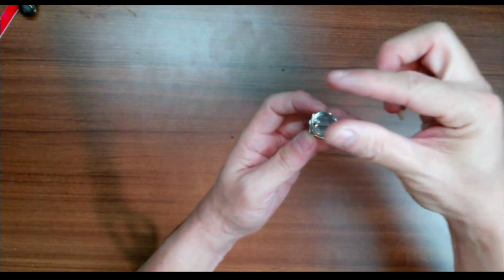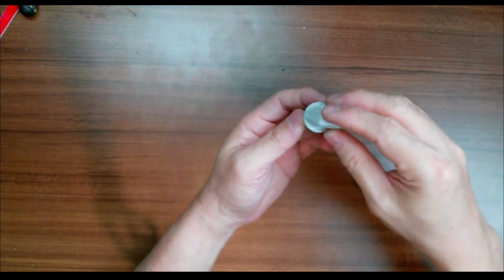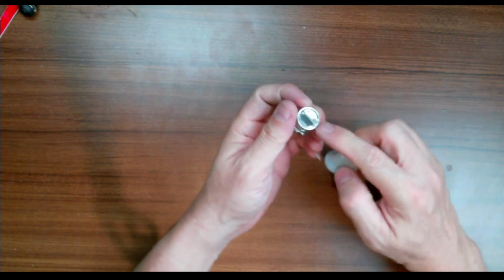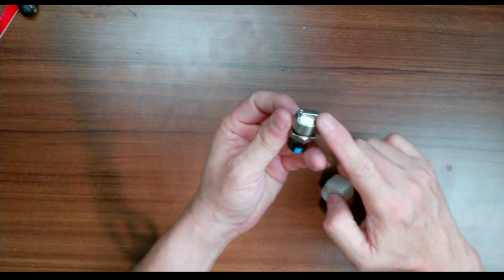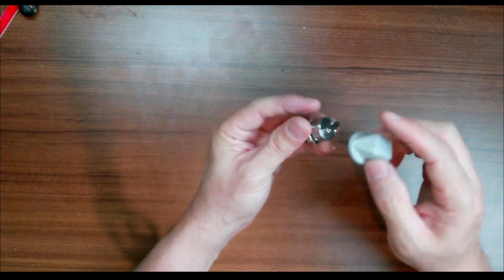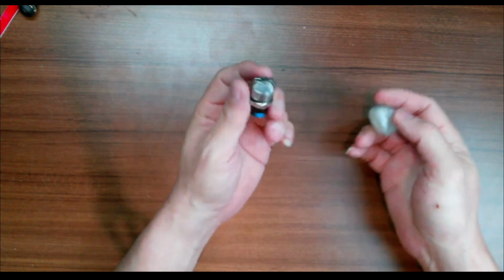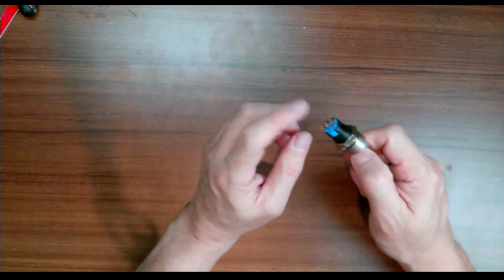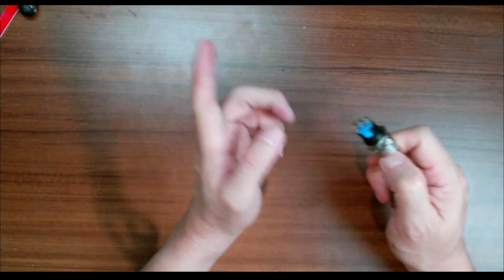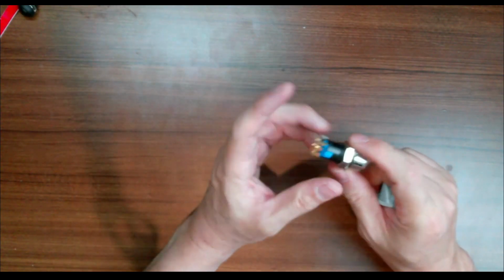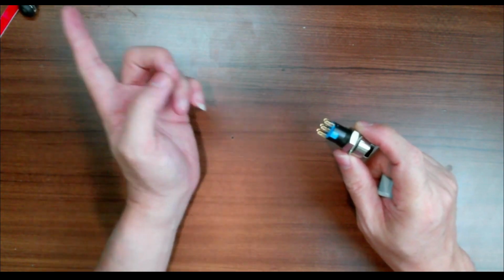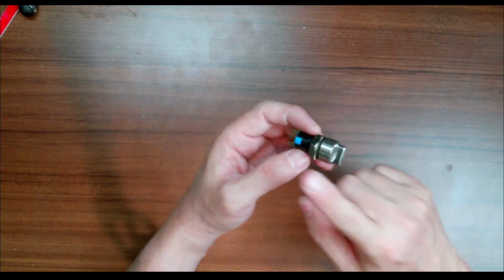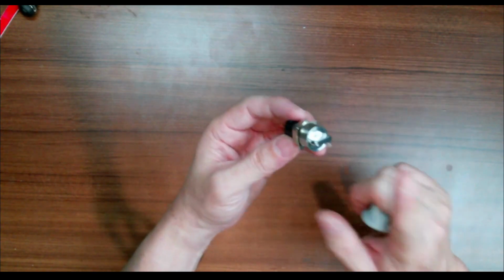From here, I put a cover like this, designed in 3D, to sit on top of this specific switch. It works perfectly well, but again, it's on, off, on. So it's similar to the 3-position toggle switch. You have to run it through a NAND gate, a logic gate first, so you get 3-position on for the wiper switch.